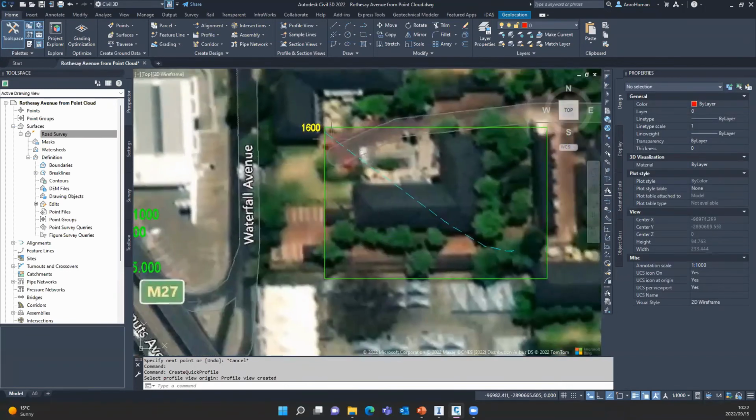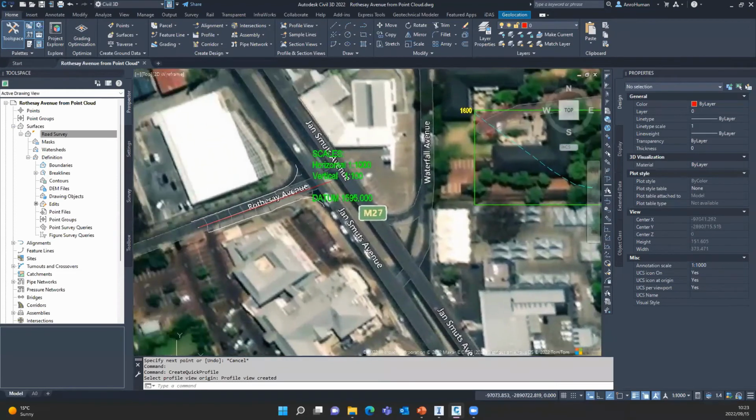And there I have a design profile of how this road center line is moving from the start towards that intersection tying point. I can then use this as a design profile to go and do my road design from. From there, you would simply go and set up your assembly and run your corridor along an alignment. And that is how you would use scan data in a BIM environment by use of InfraWorks and Civil 3D.